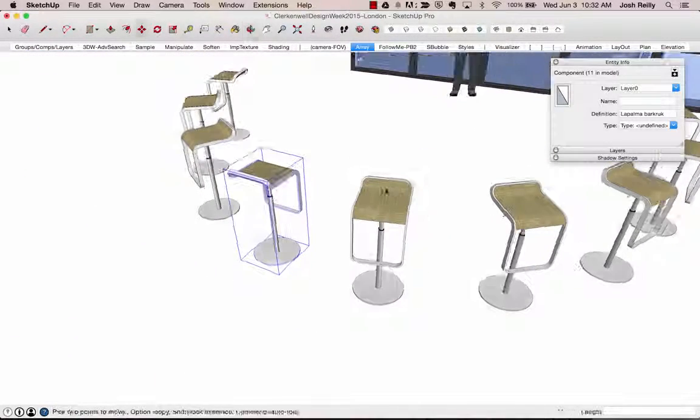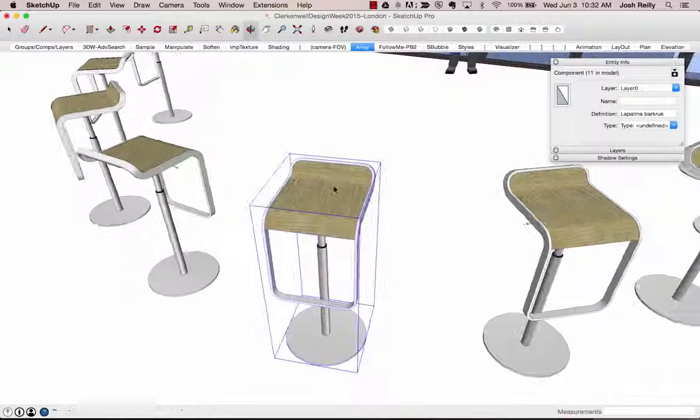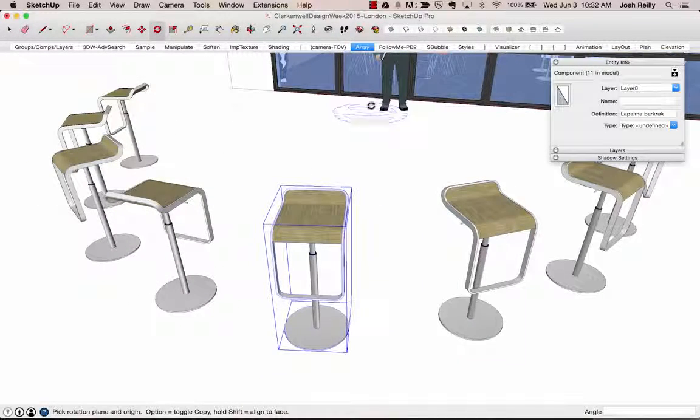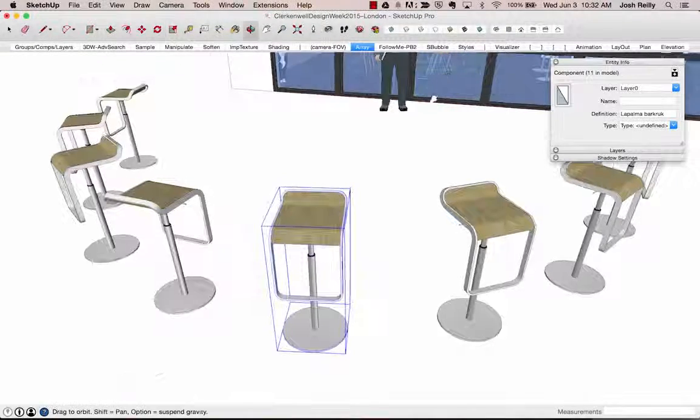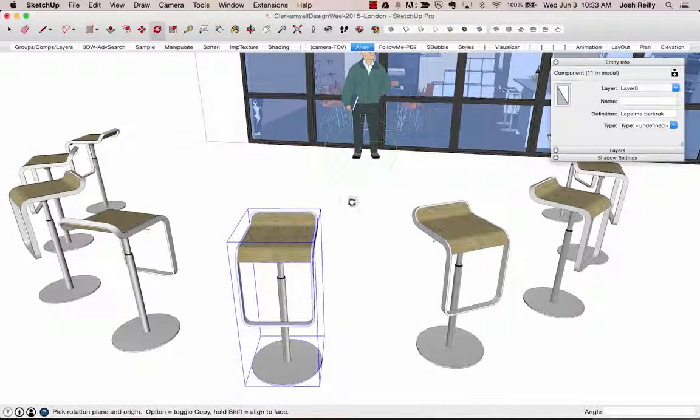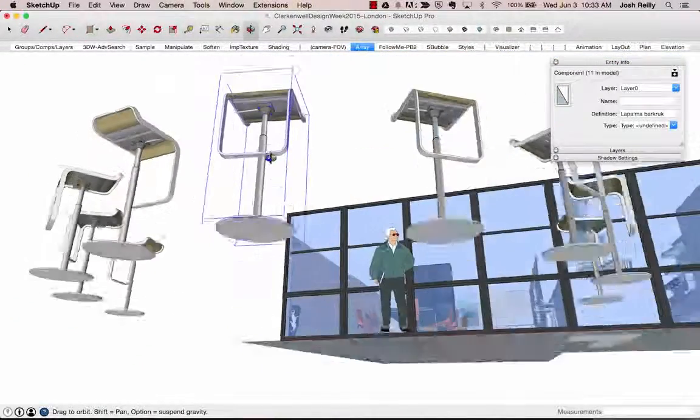If you wanted to do that with the rotate tool, you could select the object, go to the rotate tool, and with this tool, as you hover around, it changes its orientation based on where you're hovering. You can lock that by holding shift. So if I hold down shift here, you can see I can lock that green rotation plane. In this case, I want the blue ground plane, so I'll release that, hold shift here, and then make my rotation. But I actually want to go to the bottom here to find the center point.